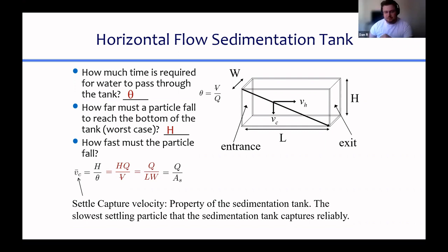Is it because the water's moving faster, because now it's shallower and shallower, so it's moving faster? It's just carrying everything straight across. Yeah, the engineering term would be you've reached scour velocity. Just like a stream carries sediment down the stream by scouring it along the bottom, it means that there's enough shear on the flocks to transport them horizontally.